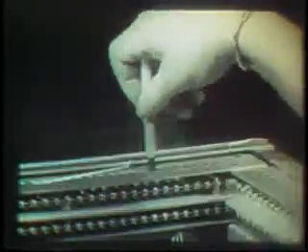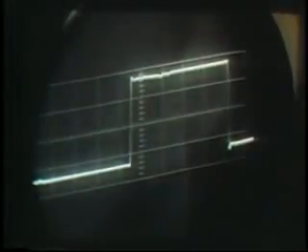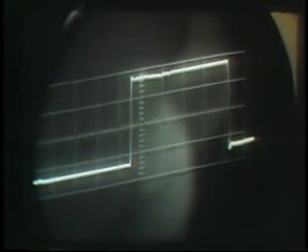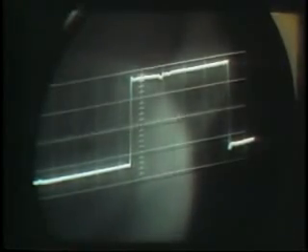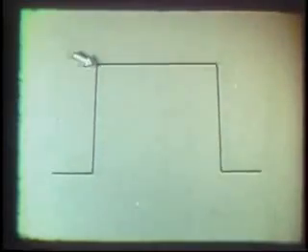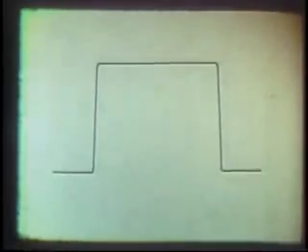These delay lines are very tricky to tune and adjust. Proper adjustment can only be accomplished with a fast-rising square wave. As we know, the speed with which the rising portion of the square wave rises depends on how many harmonics are present in the wave. A perfect square wave would contain an infinite number of odd harmonics, and the leading edge would rise from minimum to maximum in 0 time. Such a wave, of course, is impossible to produce.